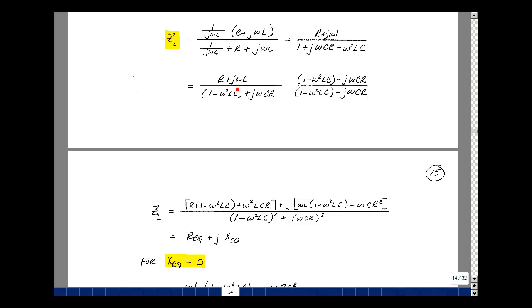For the imaginary term, it would be this times this, that's this term, and then also this times this term, so we've got a minus j omega CR, and then R again, so you get an R squared. Let's pull out that j in front. And then the real part squared, and then the imaginary part squared, inner product terms cancel. So this has a real part and an imaginary part, where here's the real with this denominator, and here's the imaginary with that same denominator.